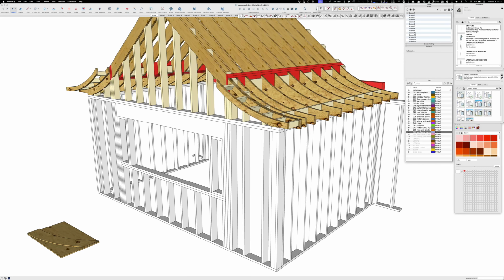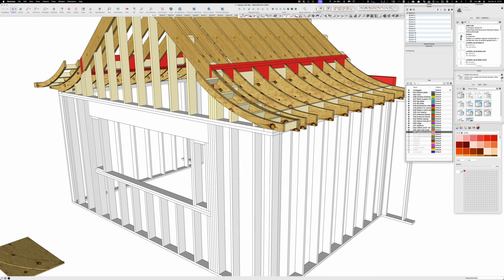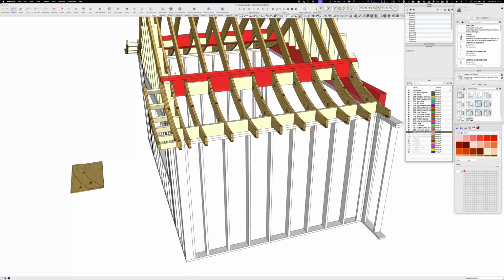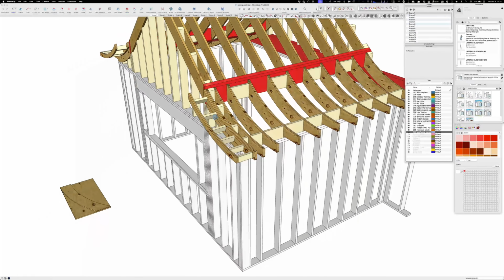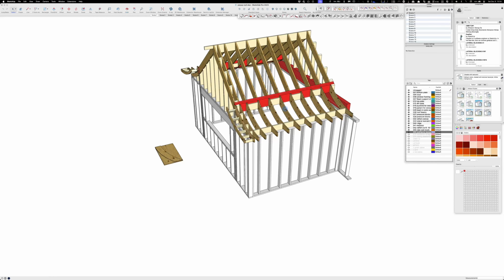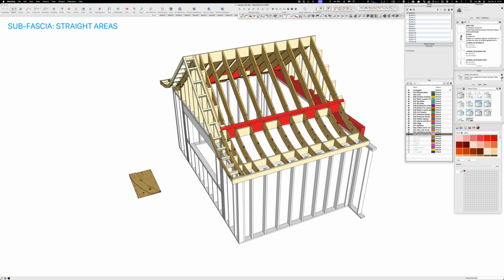So I'm sure they don't quite go the way I've got them drawn. I'm pretty sure you're going to have at least some kind of slope. But if you're using asphalt shingles, or any kind of shingle, technically, anything less than a 3 and 12 fails in doing its job. So I'm not sure what kind of material is going on here. A whole bunch of ice and water shield, and then whatever. See, it's cool. In the computer, you can do anything, even things wrong.